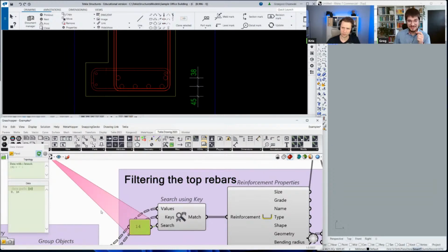And here I would just give a remark on what you, Chris, asked about those 100 drawings and some repetitive operation where you would like to insert some clouds. You have to establish some rules. And usually every company has some rules in the modeling. Based on those rules, you can filter out objects, you can group them, you can perform some drawing operations. But without a consistent way of modeling, Drawing Link is not AI. It will not just guess and propose. I think it should work like that: you have to create a specific recipe with which objects should be treated in which way. You have to have good standards from the beginning.